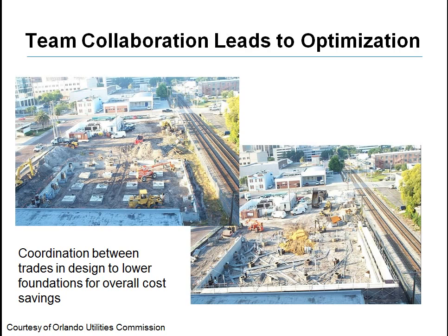These pictures are an example of the innovation that can result from collaborative pull scheduling. The excavation foreman came up with the idea of lowering the entire grade when discussing the plan for trenching with the other trades. The hauling and sand backfilling costs were a little bit more, but the saving from eliminating shoring, trenching, and faster utility installations more than offset these costs. This was a case of where spending more in one area produced multiplied savings for the entire project.